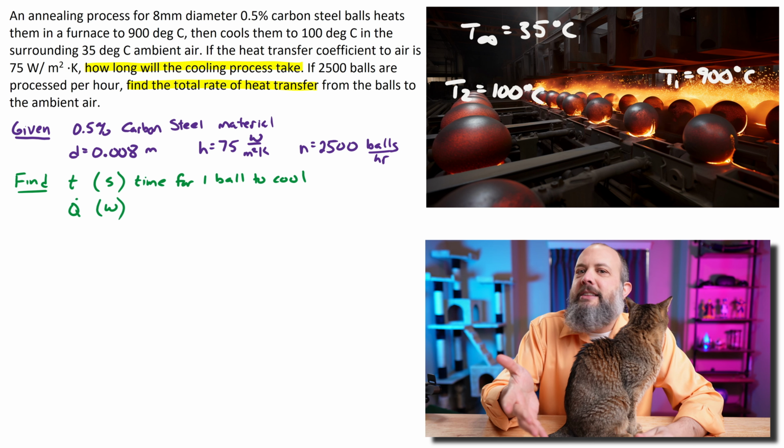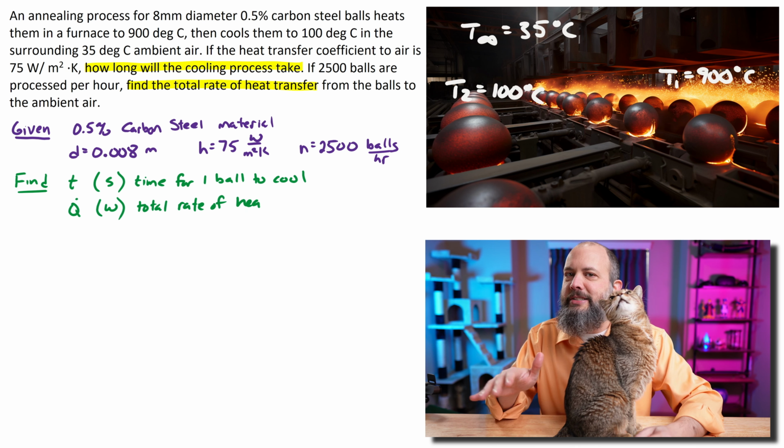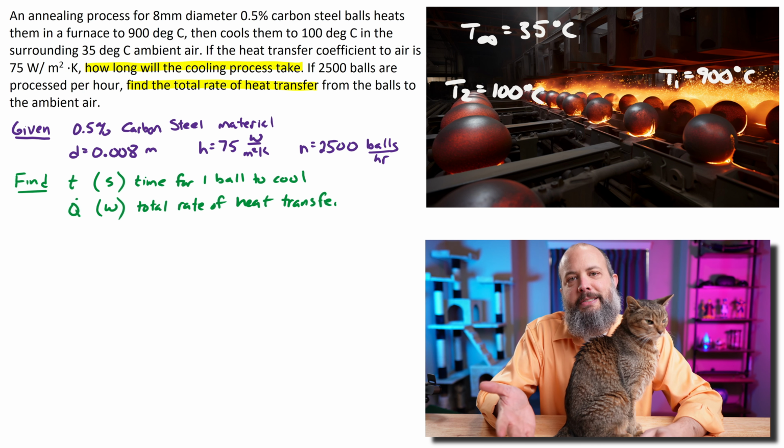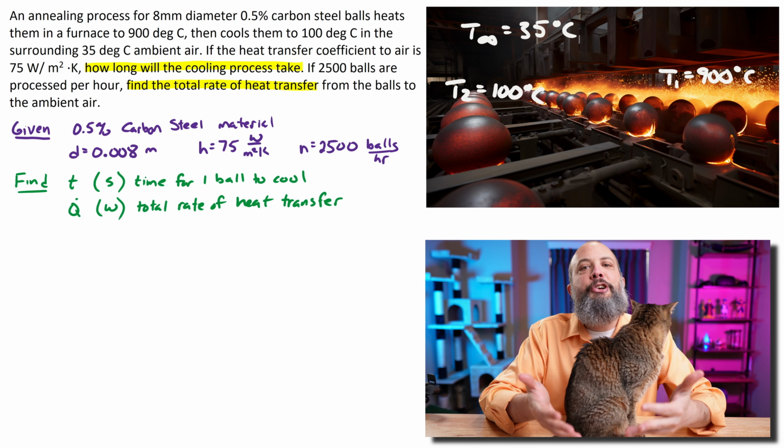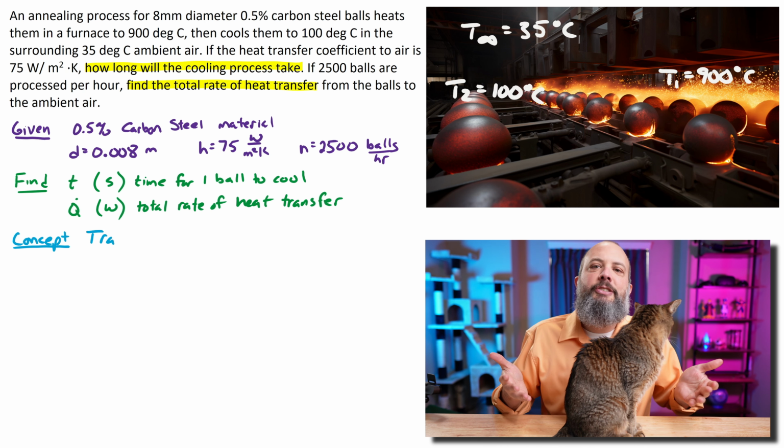And a downside to this, though, is it becomes less hard. So you sacrifice hardness to increase ductileness. And this makes your metal easier to shape. That's its main purpose. Annealing is you heat it up to make it easier to shape.